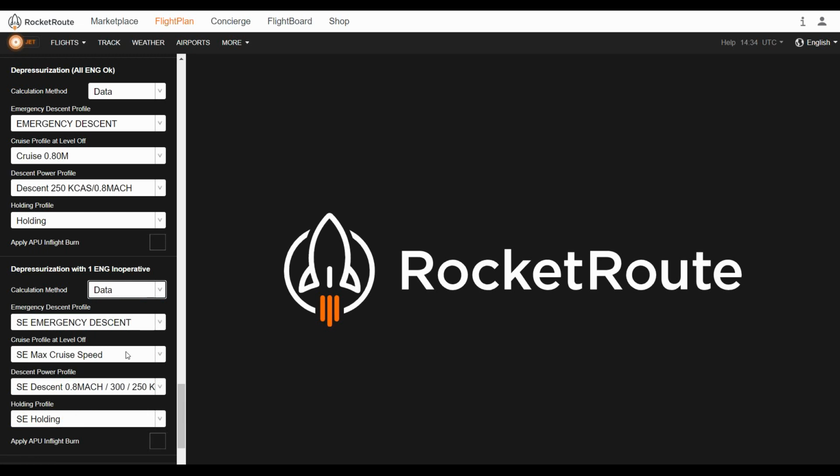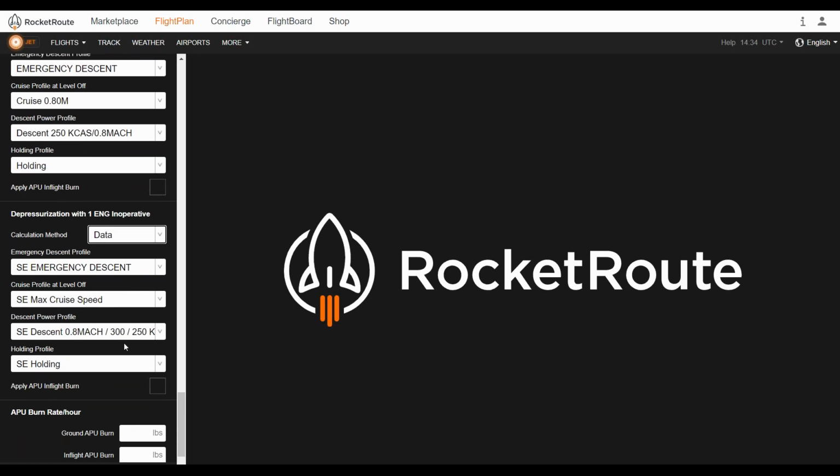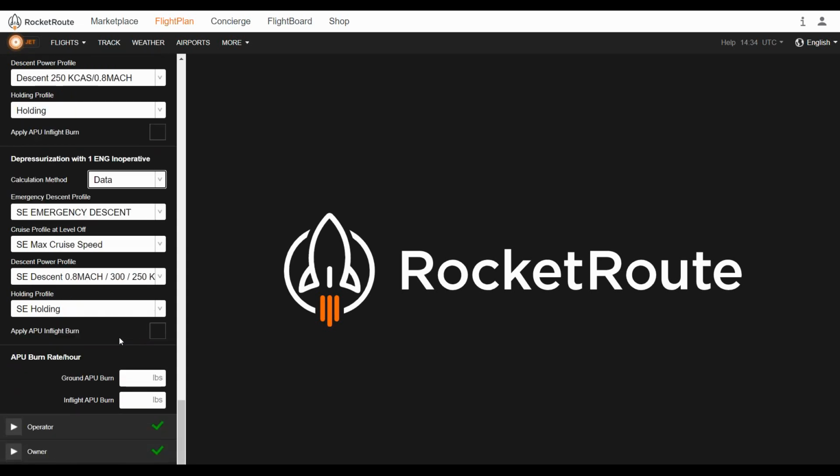And after that, you just select the cruise profile at level off, then descent profile to the en route alternate, and then holding profile, and APU burn. At the bottom, you can see you have the APU burn rate per hour. So you have ground APU burn and in-flight APU burn. At the moment, ground APU burn is not used in the calculation, and we use only in-flight APU burn.